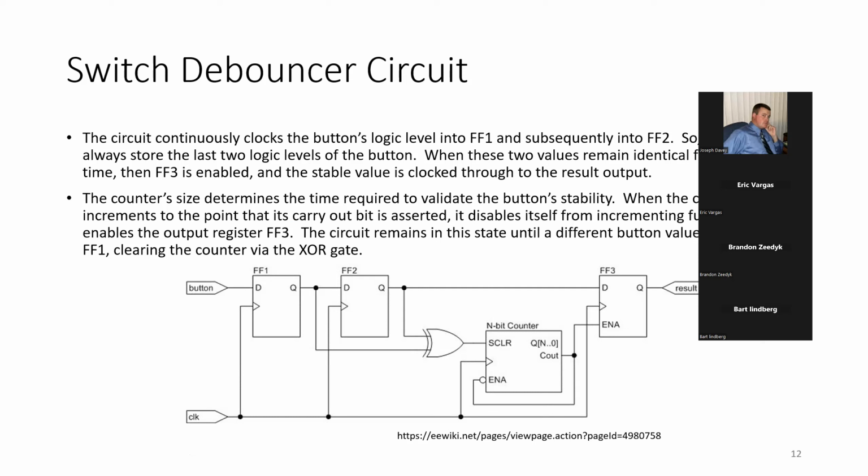So what I'm having here is a counter. If those two are identical, 0 or identical 1, I will get output here to be 0. If different, due to bouncing, I will get 1. 1 would mean clear. The counter is not working.